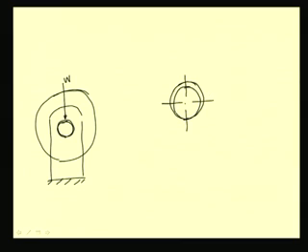So, this is the clearance that you see, and when the shaft is idle or not in motion, the point of contact is here, or along the journal. This is the line of contact between the axle and the journal. This is the weight that is being carried by this axle. So, the support reaction from the bearing block acts at this point, let it be R.